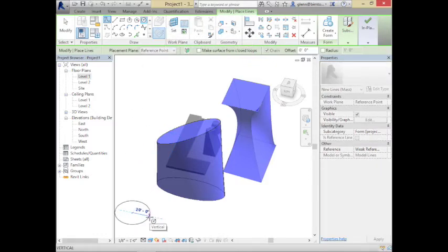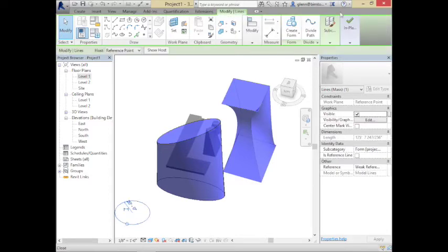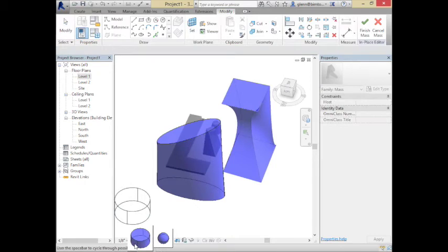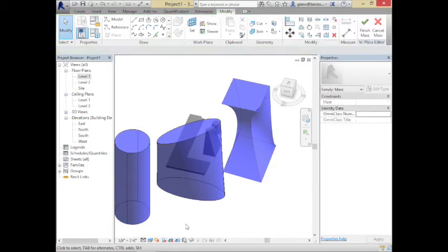If I just take a shape, and if I give a single shape, a single profile, and nothing else, and I say create a form out of that, it'll say, okay, you have a choice. Do you want it to be an extrusion or do you want it to be a revolve? It could really be either one of those. I'll make it extrusion. And it's just the same way the extrusion tool works. It's really always choosing a profile, then just sort of stretching it up.